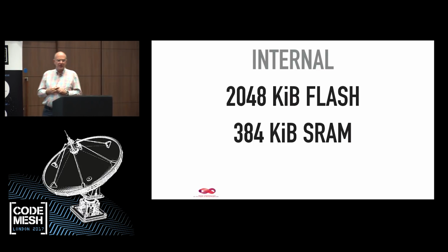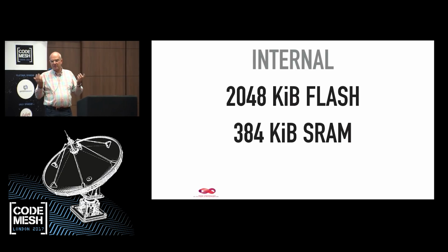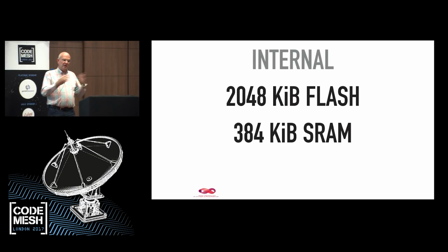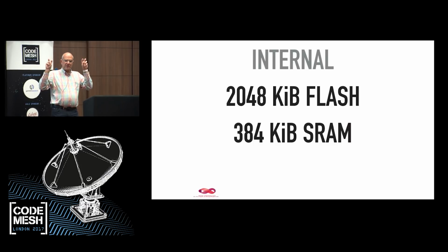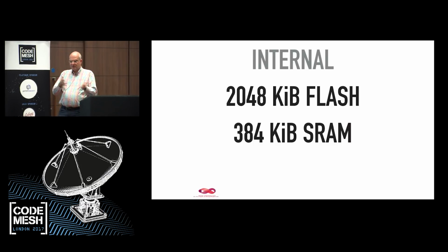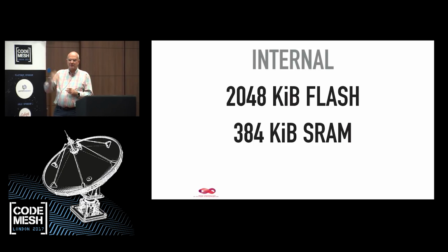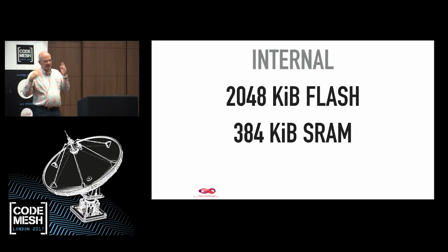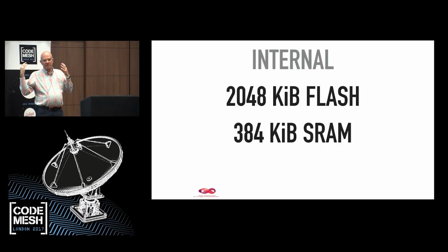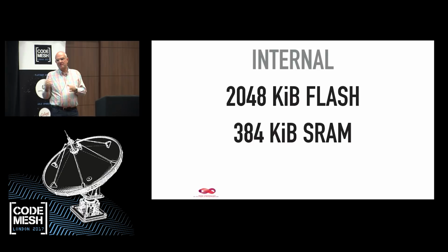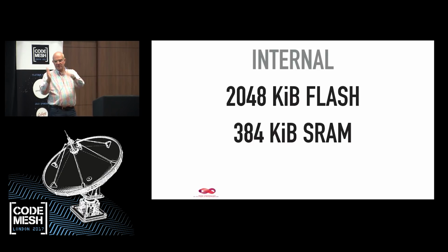The flash is actually used for the bootloader. So we have a little bootloader which also uses the same operating system, with quotes, as the actual software. So the bootloader is by us. And the bootloader basically just looks at the SD card, has an SD card driver, looks for an INI file on the SD card, and then does whatever you tell it in the INI file, which then usually is boot your BEAM